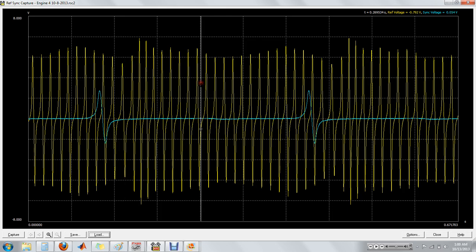So looking through here, we can see the varying levels and voltages, and this happens because as the speed of your crankshaft varies from having that spark plug in there, your voltage level is changing. Having a trigger wheel go past the sensor faster will increase the voltage level. So as we can see here, we have a high voltage level. This is actually where our peak is.